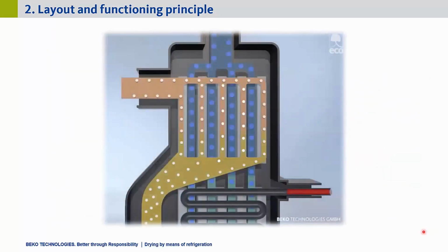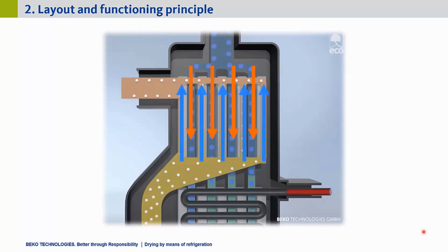So after the relative humidity is now at 100% at the bottom of the heat exchanger, the air is saturated. And the air is now guided once more over the air-to-air heat exchanger on its way out of the evaporator. And here, the actual drying process takes place. As I mentioned before, the incoming warm air is pre-cooled by the outgoing cold air. But it is also the same case vice versa. So the outgoing air is reheated, and that is the key. By warming the air, it can carry more water vapor again, and thus the relative humidity decreases.